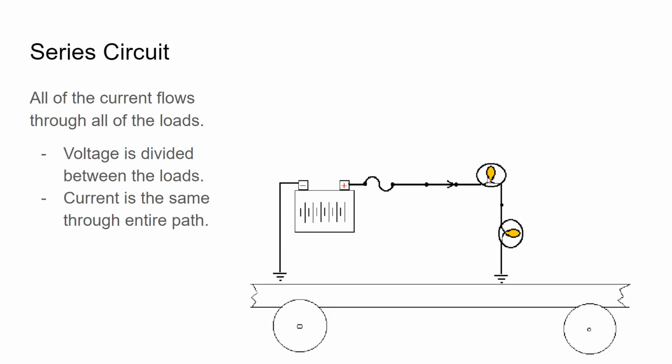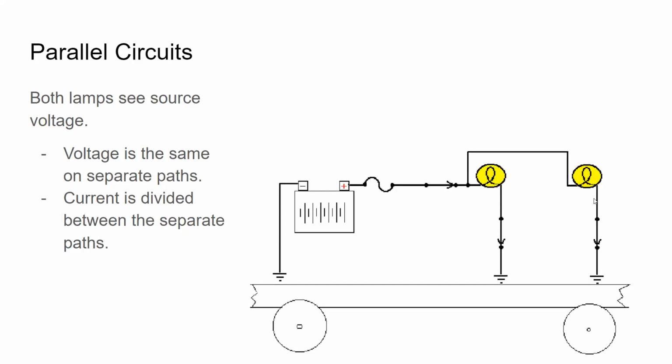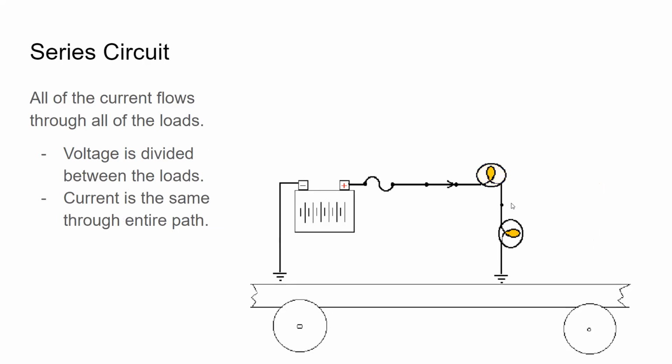Each load on a circuit, for example, in this case, a light bulb, each load consumes voltage. If these bulbs are completely identical and they have the same amount of resistance, which, in terms of an electrical circuit, is resistance to current flow, both these bulbs have the same amount of resistance. In this case, when they're fed 12 volts, they want to consume 1 amp. It takes electrical pressure or voltage to push through a resistance. And a resistance is an obstruction to current flow.